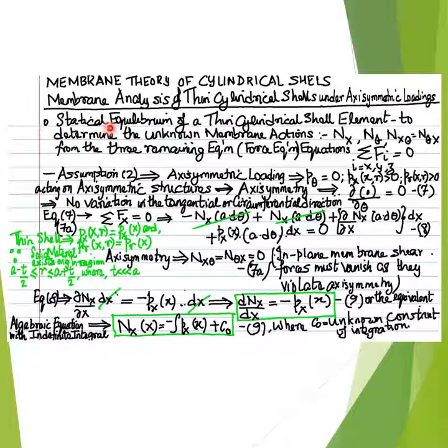Also noting that the membrane solution of the unknown internal in-plane or membrane actions nx, n theta and nx theta is statically indeterminate because of the variational terms emerged in the statical equilibrium equations derived in the previous slide based on the considerations of the statical equilibrium of the differential thin cylindrical shell element.